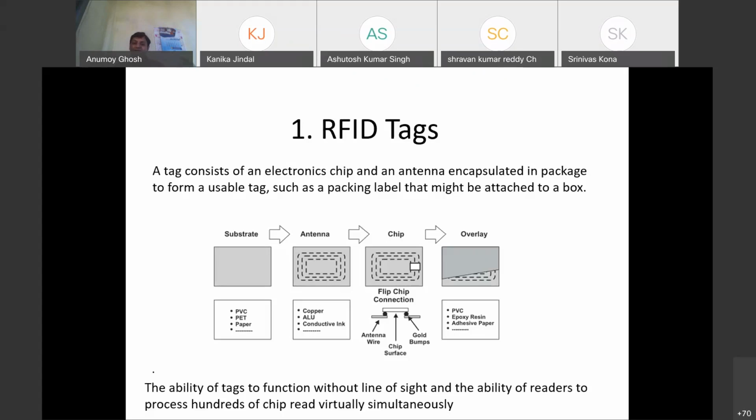Then the incident wave and the reflected wave will superimpose, and there will be a standing wave formation. If there is a standing wave formation, there is no progression of power. The power gets stagnant within a confined space, so there will be some loss of power. That is why the chipset and the antenna impedance should be matched. That is a very important thing.